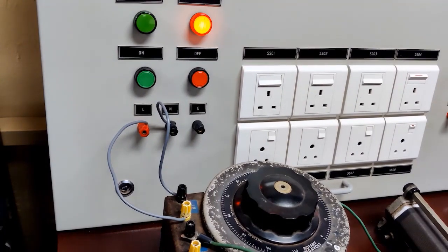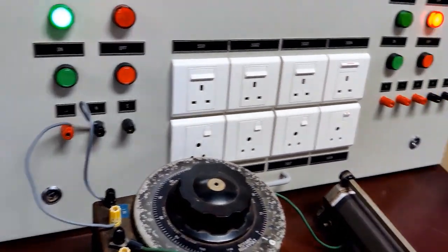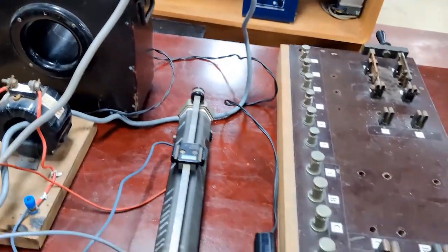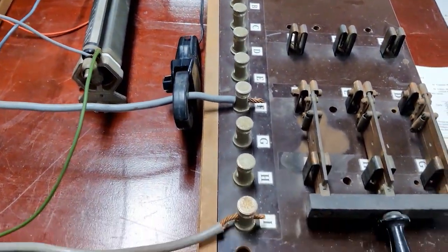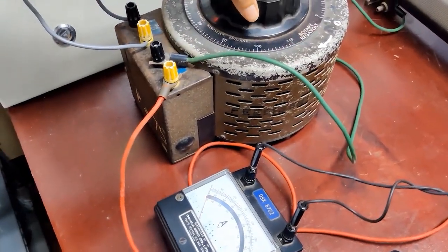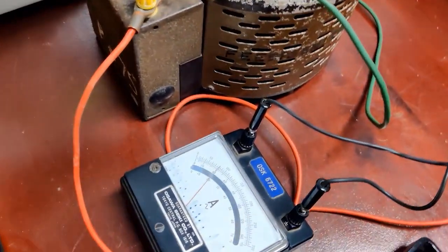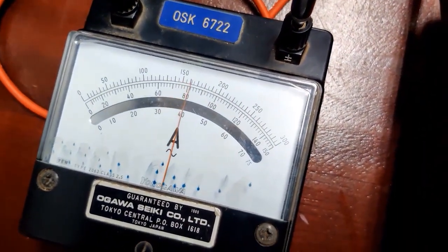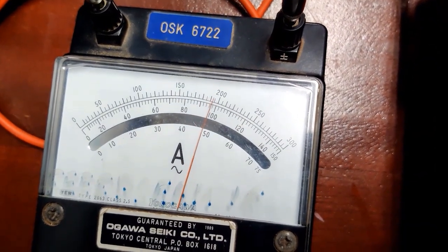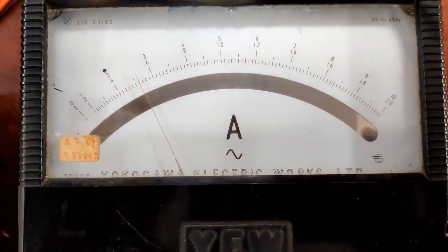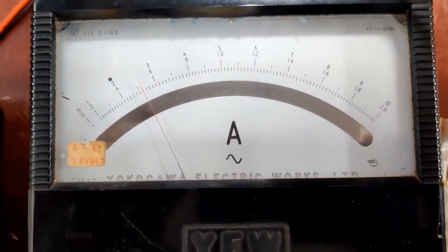Now, turn on the circuit, keep that switch open and this switch closed, and then, as in the previous step, rotate the dial so that we have a primary current of 50 amperes. And then take the readings of the ammeter and voltmeter and write them down in your observation sheet.